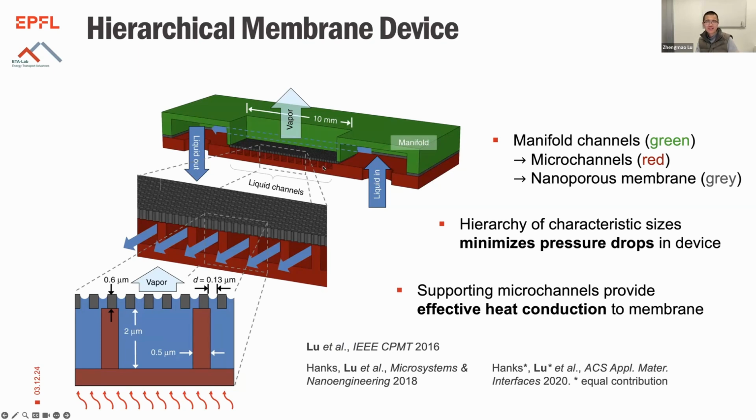And in the smaller structures, you have the size scale that's helping you suppress the nucleation. The way we can verify this is we don't see any pressure oscillation in our liquid supply for this microfluidic system. But the principle is basically pressurization.